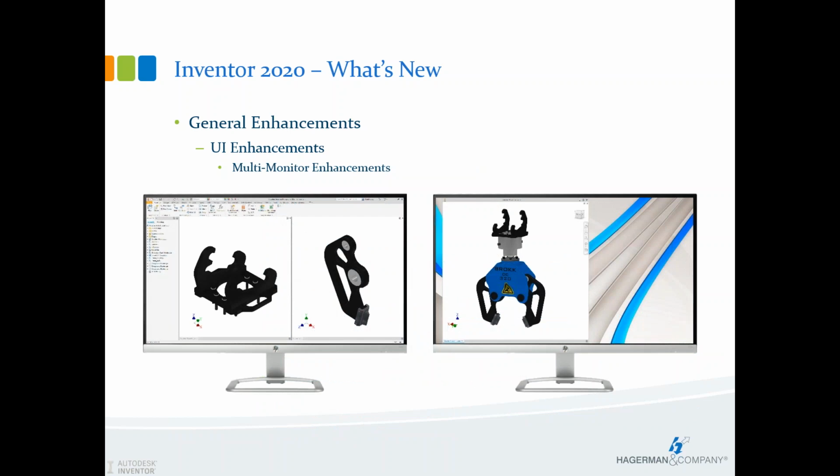We've got some multi-monitor enhancements for Inventor 2020. Now, Autodesk has been supporting multiple monitors for a number of years with the software, but what we're talking about today with 2020 is the fact that you can now dock the files on a different monitor. So you can take the model tabs, where they're listed down there in the lower right on the status bar area, drag those to another monitor, and resize them. It remembers where it was.